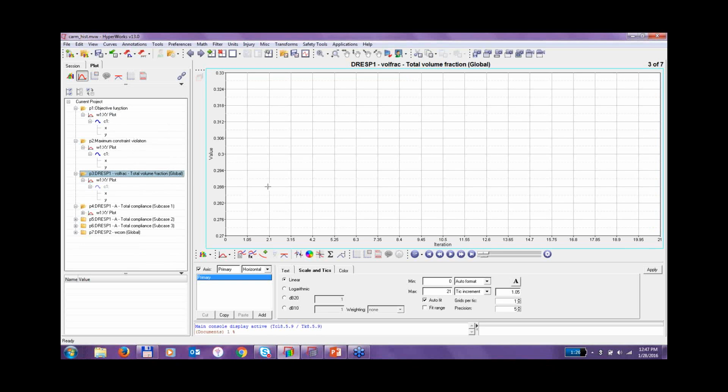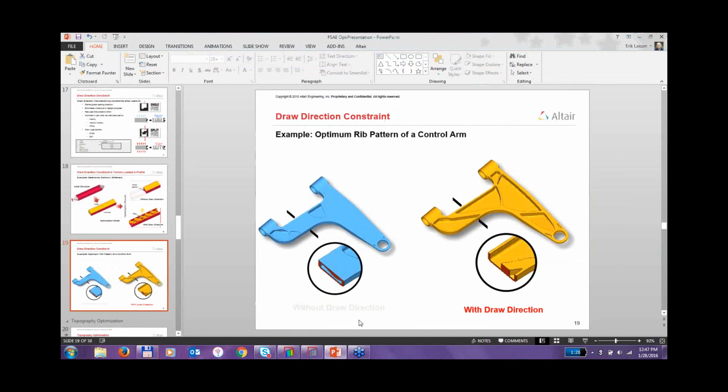What typically it should show me is how that is going away, but apparently it's not showing me a chart for that. But essentially, I'm telling it, remove material, and at the end of the day, you better not have more than 30% of the material that was there to begin with by volume.